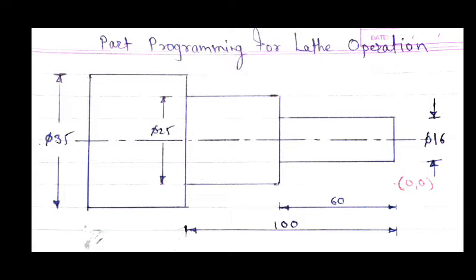Also, modification in the program is difficult in NC machine, whereas modification in the program of the CNC machine is very easy. As we know, with punch cards modification is difficult, and in CNC you can modify the program. We have seen in our previous lecture that we can keep a gap between blocks, that means N05, N10, N15, N20. If we want a modification in between them, we can insert a block in between. Say if we want to do some operation after sequence number N15, then we can give the number N16, then you can do the further process, that is N20 and N25, by following the sequence number. In such a way the modification in the program is easy in CNC machine.